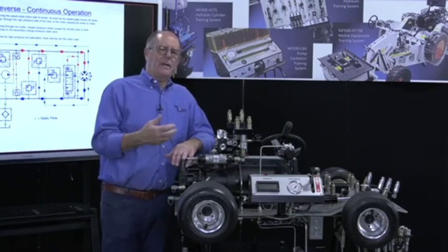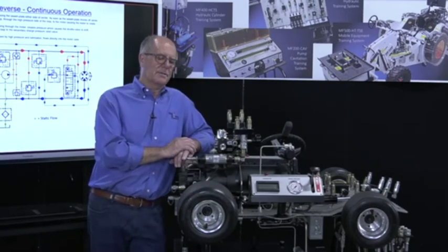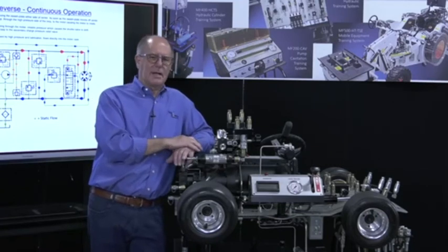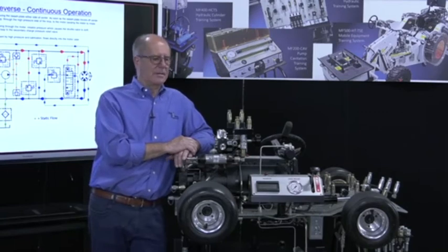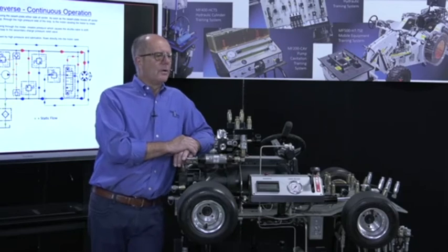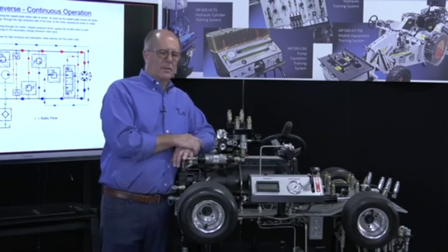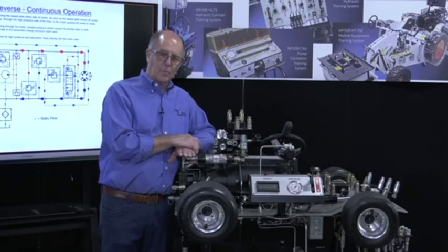Now, what I cover in the articles I've written about post-catastrophic failure startup procedures also covers steel lines. Because if you're out in the field and you've got steel lines on a machine, like on an excavator, I'm sorry, folks, you're not going to be replacing every single line on that piece of equipment. Let's be realistic. So what we do in that case is we replace the pump, and yes, we replace the motor, but what you do is you loop the lines at the motor. And I don't care if they're split flange, it doesn't matter. We've got all the stuff to do that with.